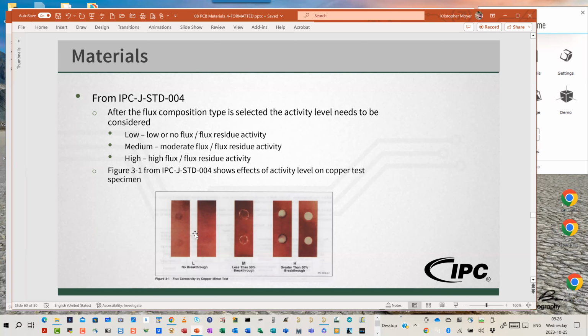Think copper piping, or think 2-inch square copper lug bars for connecting to mains power in our three-phase wiring coming in for the mains lines coming off of the transformers, or things of that nature, where I have enough material. If I'm talking printed circuit boards, my copper is only 1 mil thick or half a mil thick, 1 ounce and half ounce copper. If I start putting those highly corrosive materials on there, I'm just going to dissolve my copper completely off the board.